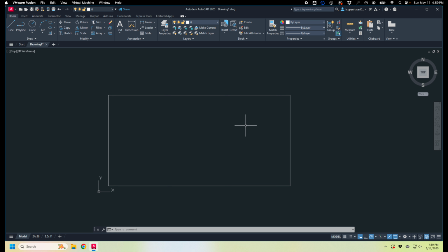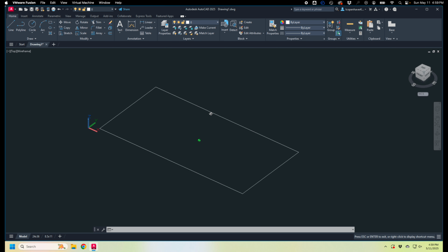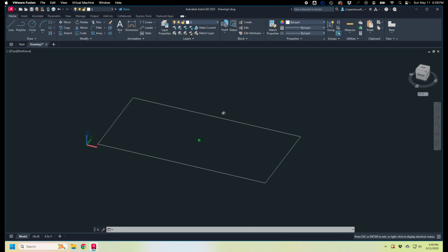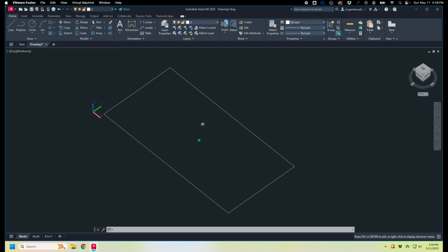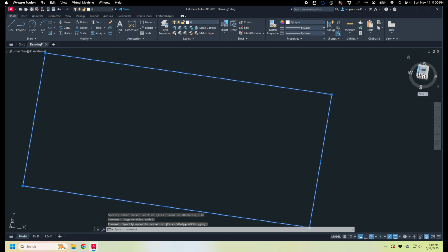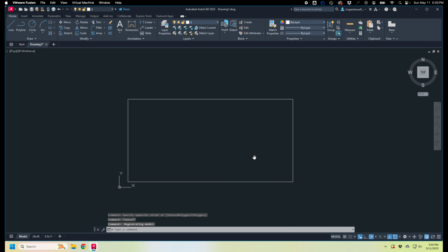When we get into three-dimensional drafting or three-dimensional modeling, you're also going to add in the shift key. So shift will let you rotate around an axis. When I hold shift and then I click and hold the center wheel and then drag, that allows me to manipulate the third axis and rotate around a point. And the point is that green sphere in the middle right there. Truthfully, we're not going to get to that for a while, so I'm just going to go back to the flat view by going to my view cube and just clicking on the top. And that brings me back to that flat view of the XY plane.